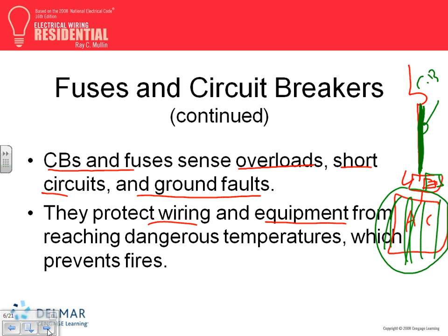And why do we protect from overload, guys? Who cares? If this cable is supposed to carry 100 amps, why can't I make it carry 1,000 amps? If you don't care about smoke coming out of the installation and fire in your building, not a big deal. If you put 1,000 amps into a 100 amp cable, what's going to happen? It will carry it momentarily, guys. It will carry it for a couple of seconds, but eventually it starts heating up because high current creates heat, until smoke starts coming out of the installation, and hopefully by that time it shorts and the circuit breaker will wake up.